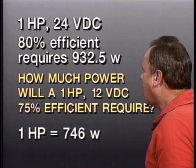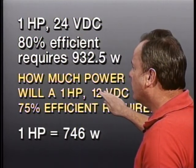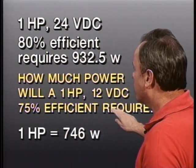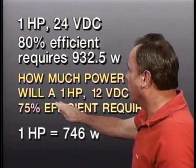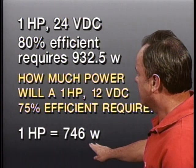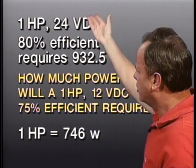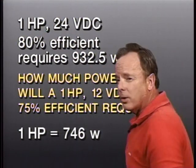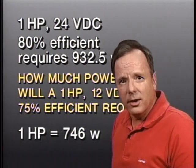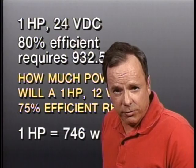They're going to ask you, how much power will a 1 horsepower, 12 volt DC electric motor require if it's 75% efficient? How much horsepower or watts will be required to produce that 1 horsepower? And they also tell you that 1 horsepower equals 746 watts. Now you might look at this and say, hold it, wait a minute. What does this top part have to do with this question? I've got the information I need right here, don't I? And the answer is, this top part had absolutely nothing to do with the question. They just threw that in there to confuse you.